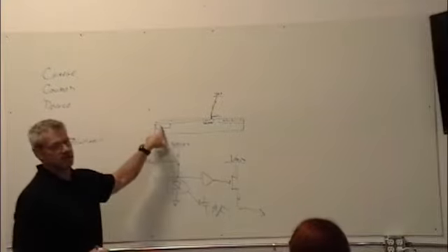That's not even a 25% fill factor. The fill factor was very low. Now if you think about that, I've got a lens coming down on this, focusing on this image plane, and my pixels are here like this, but I'm only really getting maybe that much of them. I'm wasting a lot of energy.